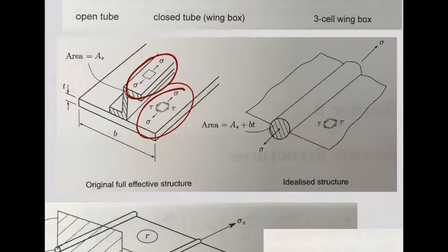So you have the stiffener here carrying a direct stress. What we are going to do is build an idealized, simple model where you have the skin carrying only shear stresses, and where you have what we call a boom, with circular cross-section, and this boom carries only direct stresses. So these two structural elements have a very different kind of behavior. The booms carry direct stresses from bending, so they carry the bending loading, while the skin carries the transverse shear or shear flows, okay?